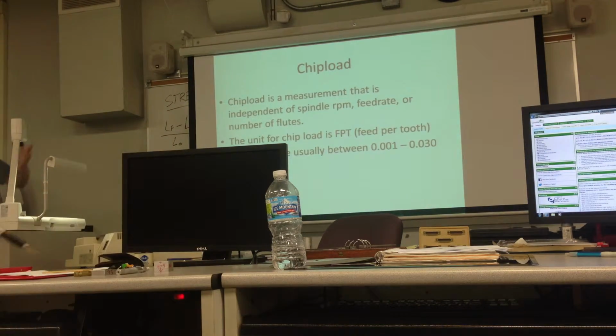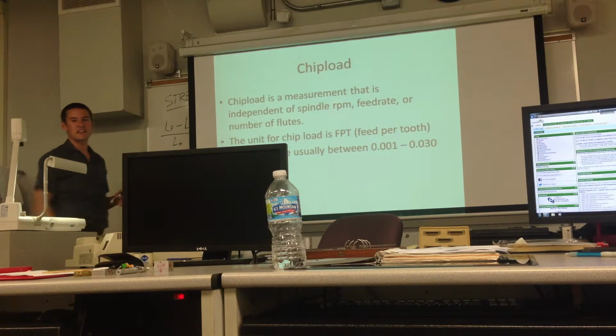So that means if my chip load increases, they're all multiplied, right? So that means my feed must increase. So IPM, inches per minute, is your feed rate. That's how fast you're feeding into the material. Okay. We'll get to that.